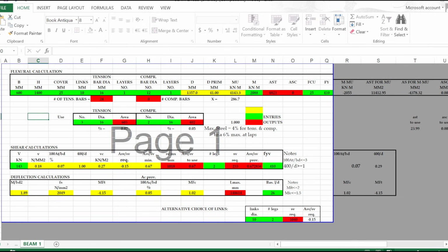Very good. Now you can see here now that the software is also operating with this principle. At the end of the day, the moment capacity of the section that was needed for the 20-meter span beam to pass is actually way greater than the moment in which the beam is actually generating based on the load condition that's acting on the beam. Now, you see now that with this, your 20-meter span beam is actually okay in terms of the moment. Now, let's look at the shear force.